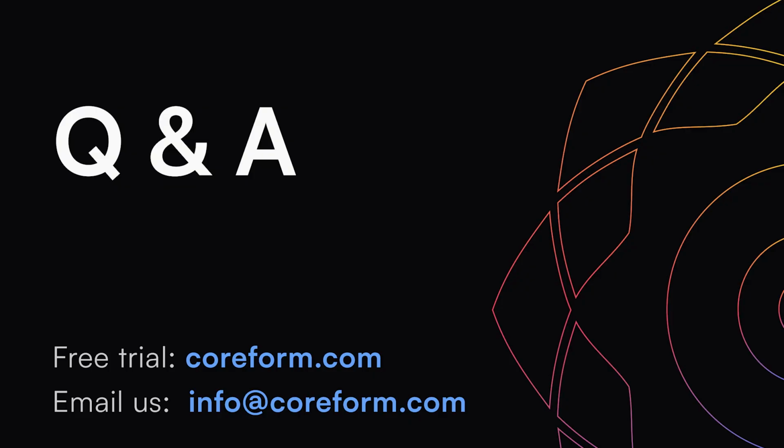Yeah, so one quick thing is I will say that we don't consider our method to be a meshless method in terms of the noun of a mesh. We definitely have a mesh. The mesh provides efficient computations for stuff like, how are my degrees of freedom ordered? How can I do assembly quickly? So we definitely lean into the fact that there is a mesh. It's just trimmed, and we just generate it without you having to perform meshing tasks. So that's one area that's different from, say, peridynamics or a material point method, where we really do have a finite element mesh in the Lagrangian form.